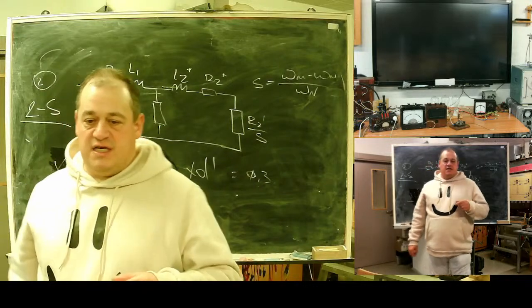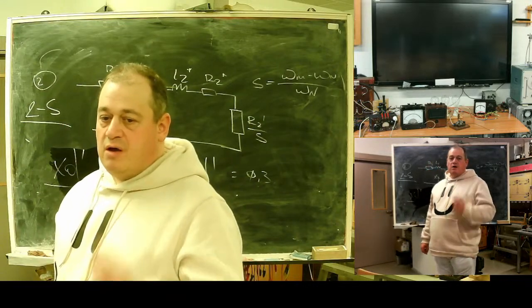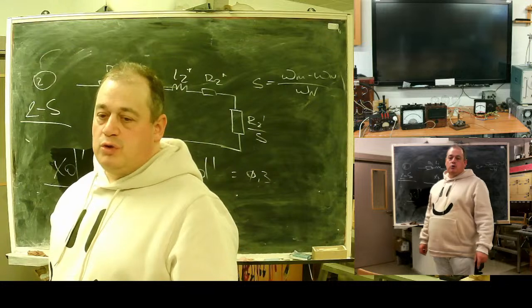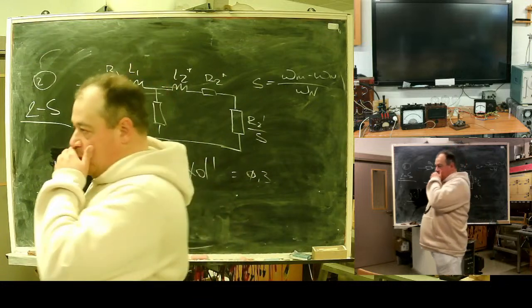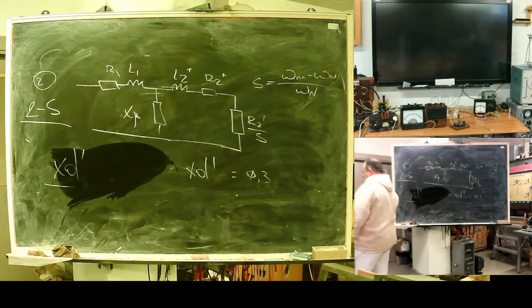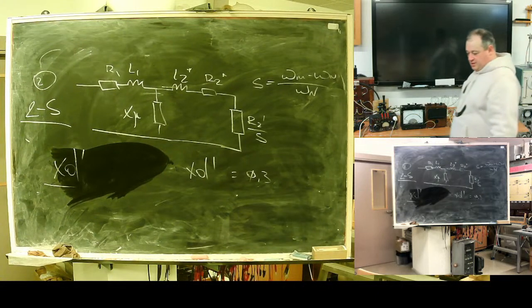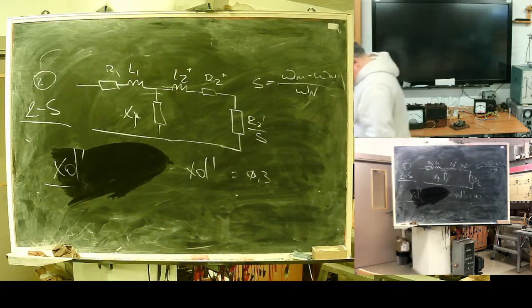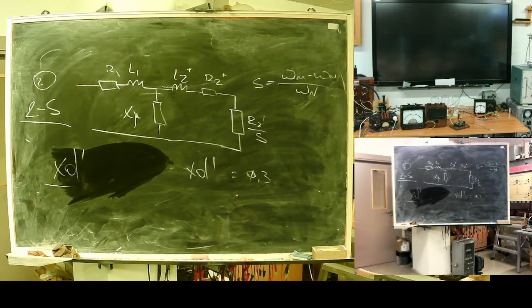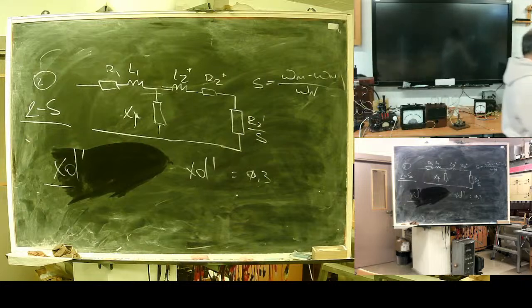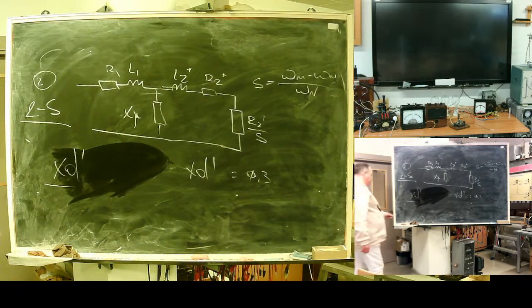For zero sequence, it is always infinite. Do not try to ground the central point of a synchronous machine. It will die, and die shortly, because of rotor overheat. I left you to think why.